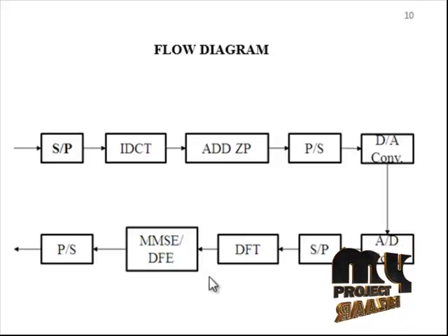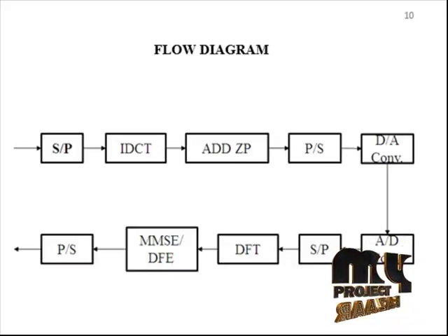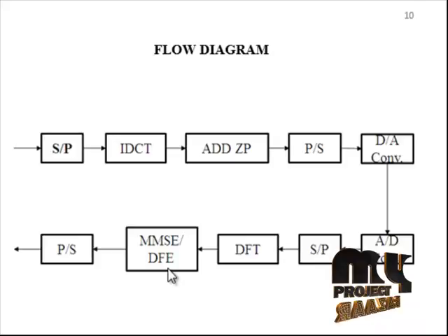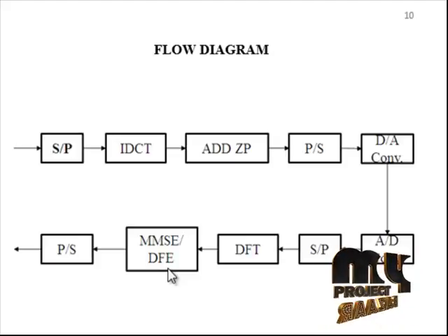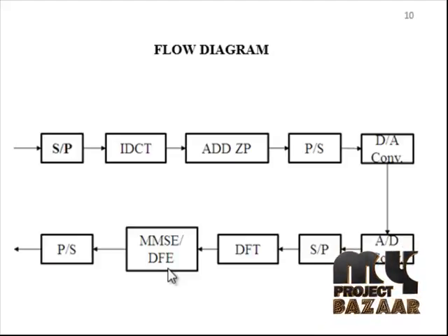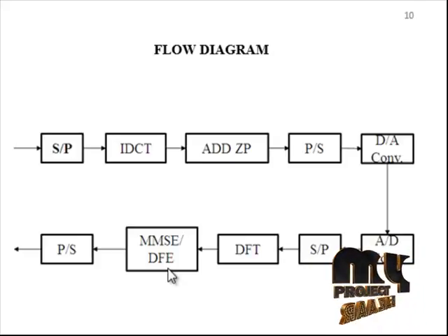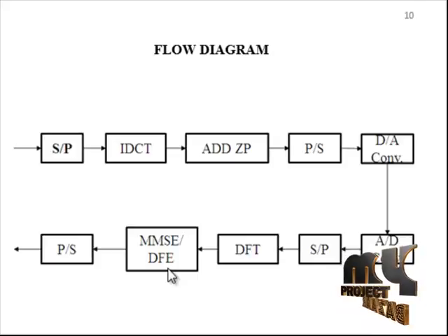Next, the simulation of FDE based ZF and MMSE has been performed. Frequency domain equalization is applied to the single carrier modulation solution. OFDM combined with time division duplexing using minimum mean square error frequency domain equalization has been considered. The linear equalizer aims at minimizing the variance of the difference between the transmitted data and the signal at the equalizer output.